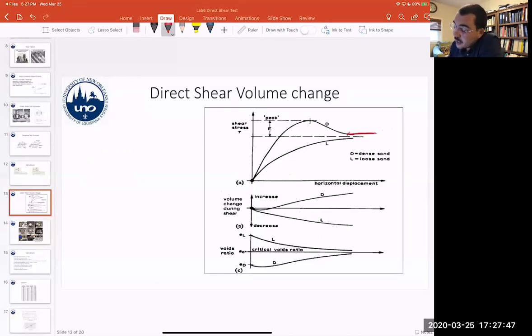And that's what sometimes in design depends on what kind of conditions you're having. Are you having short-term conditions where you will use peak strength, or long-term conditions where you'll use the residual strength? So this whole initial time, it's just the strength of interlocking between the particles, and then this is where the behavior is purely frictional.